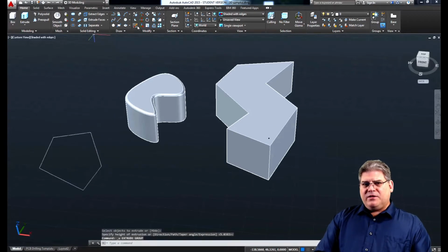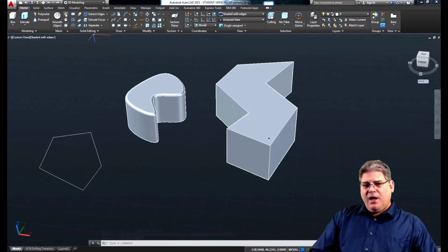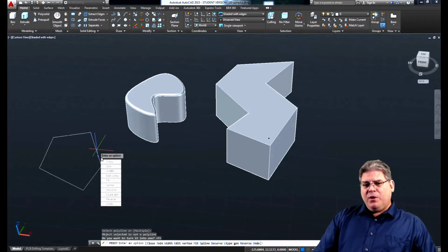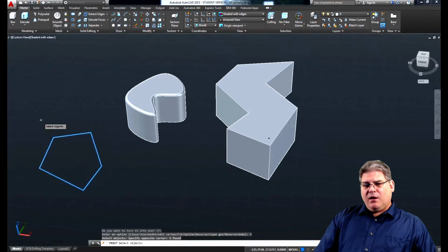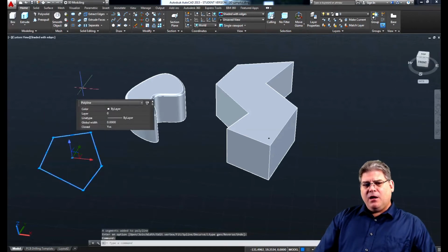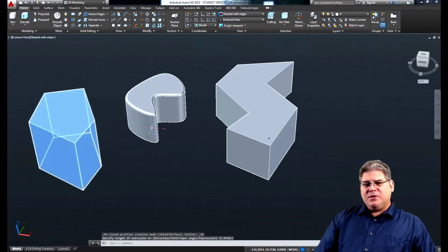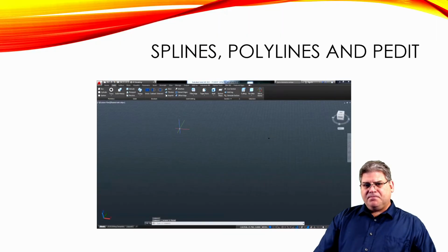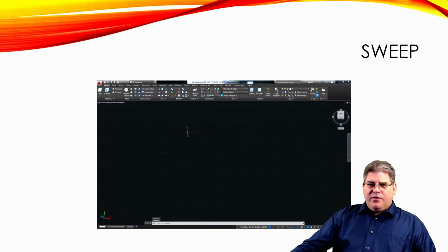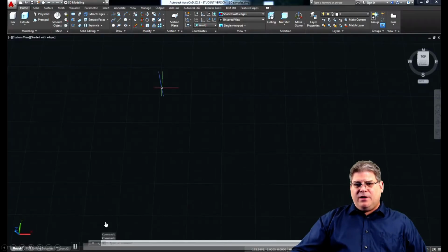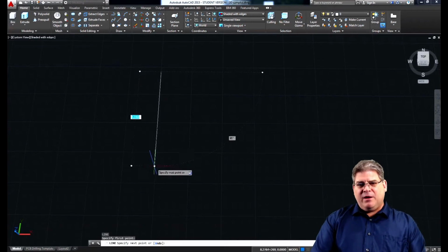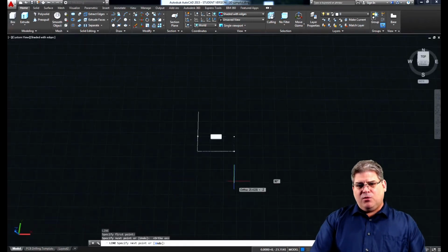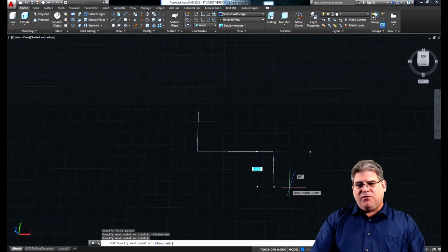Note that when it's not closed, one closed entity, and I tried to extrude that, it came up as those like walls, and so those are actually surfaces. So we need to make sure that we use a command like Polyline or PEDIT to turn it all into one object so that it becomes closed. Okay. The sweep command is really cool. Again, I don't expect you to start off being able to run this, but note that it is an option for you.